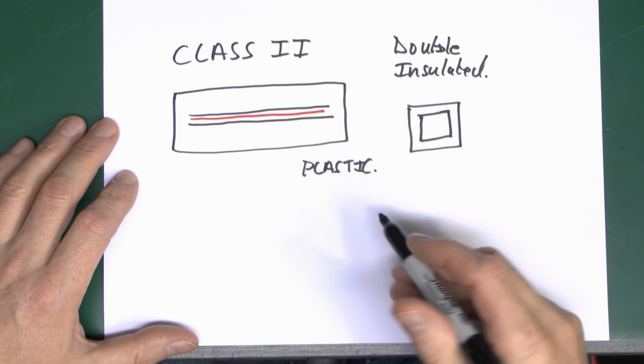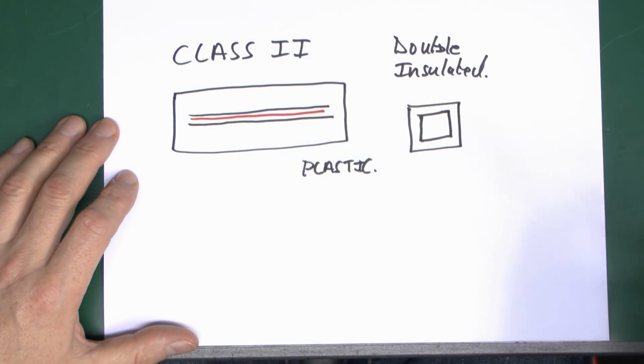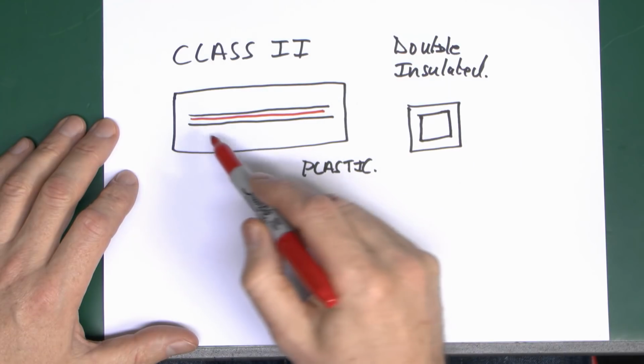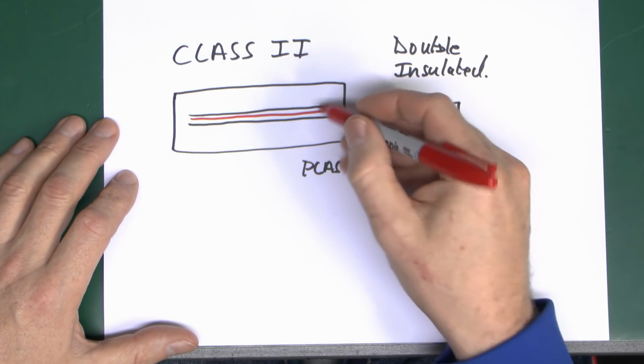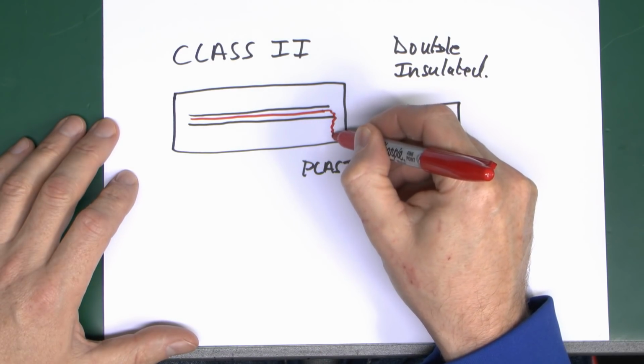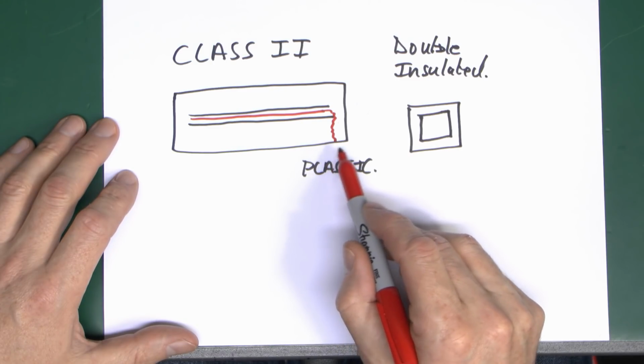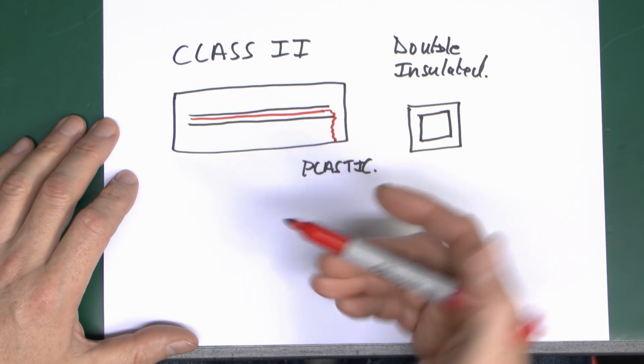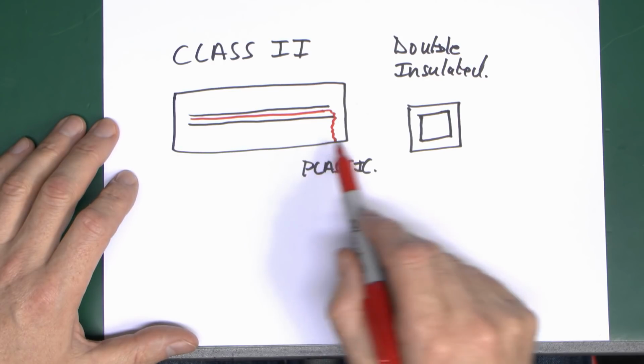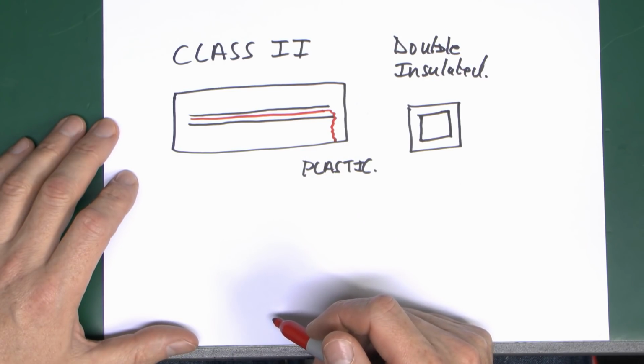The idea with this one is very simple. Got the conductors inside there. If this insulation should become damaged inside or something happened in there, this live part could come out. But if it contacts the outer casing or the second layer, nothing actually happens because of course this is an insulator. So again, nothing happens, no one gets injured or shocked from it.